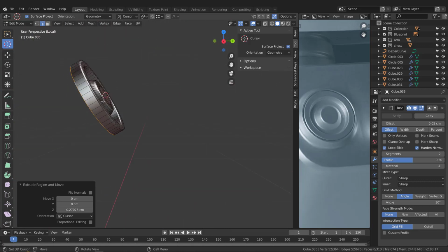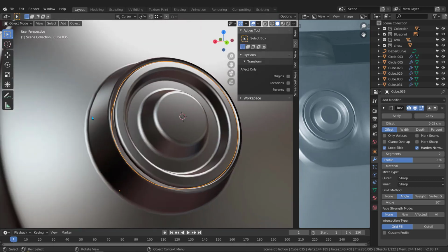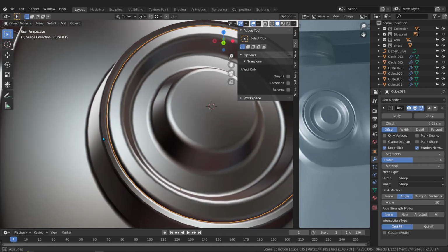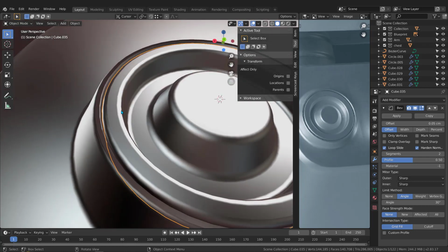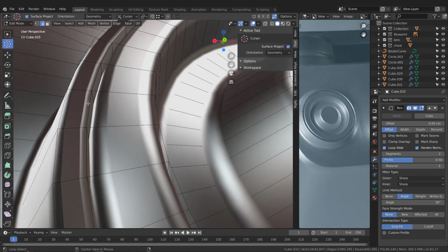Well, now let's hit slash, and I got this result, but I think I got some overlapping right here, because this area is very close, this edge is very close to this one. So I will select this piece and then hold Shift to grab this one and tap to the edit mode. I will select both of these two edges.